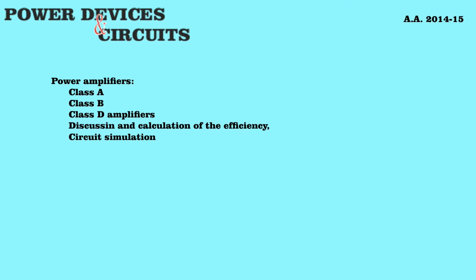The ratio between the maximum power dissipation of the power device and the maximum power transferred to the load will be 0.40, or 40%. Good, better, but not so good. The total power dissipation on both devices is 40%. Each device needs to dissipate 20% of the maximum output power.